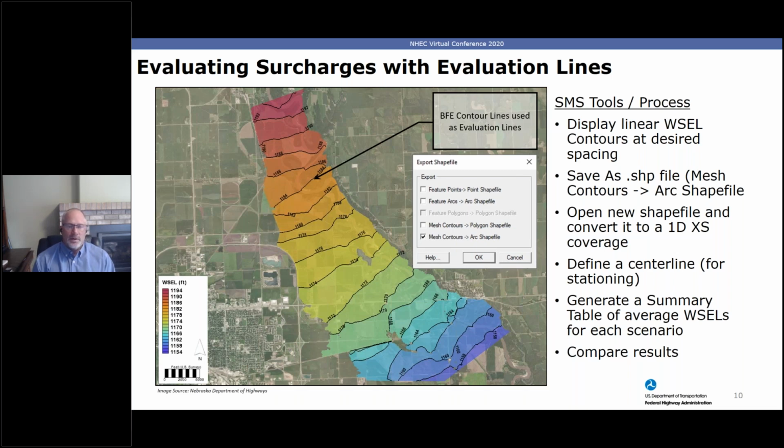Okay. Typically, a peak flow is used for 1D delineation, which gives the conservative sense to the analysis. How does switching to unsteady state impact the conservativeness of the floodplain delineation? Well, switching to the unsteady, if that's what the community or state is going to require, does change the delineation.